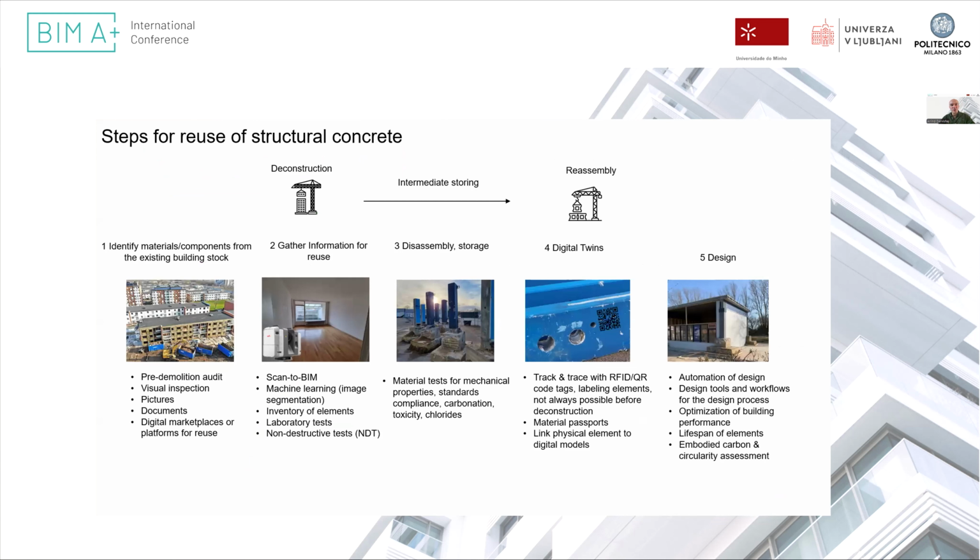When we look at reusing structural concrete, there are some databases coming up, but initially design is the last step, and the first step is identifying elements or components, either through a database or in the existing building stock, buildings that are planned for demolition, and gathering as much documentation as possible that exists out there, or gathering this through scan-to-BIM approaches, machine learning, and conducting laboratory tests or non-destructive tests to guarantee the quality of these materials.